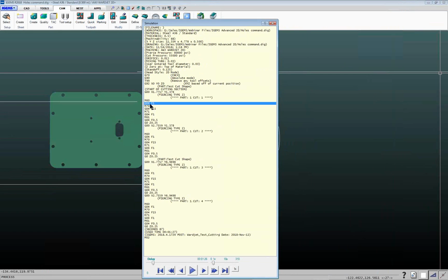So in this case here, it comes over, turns our water and abrasive on, sits there for 15 seconds, and then turns the water and the abrasive off. So that one there, you'd pierce all the way through, with the idea of using that as a point to locate off of with the drill off the machine later.